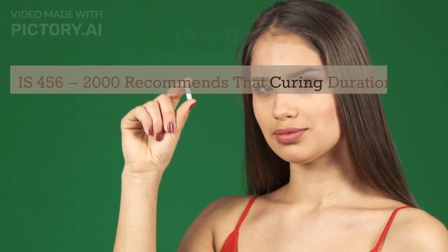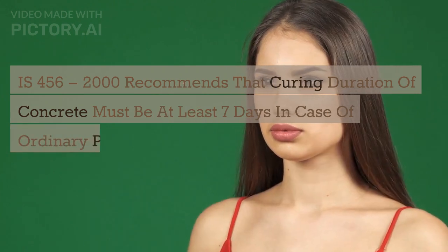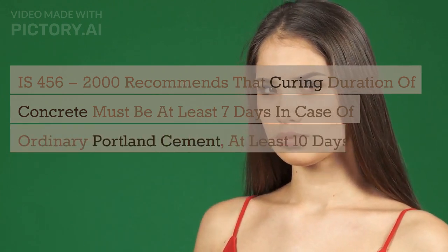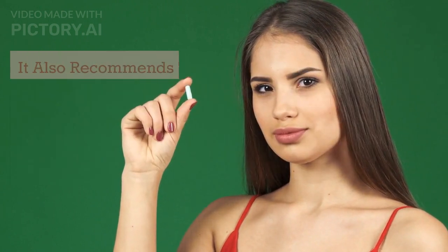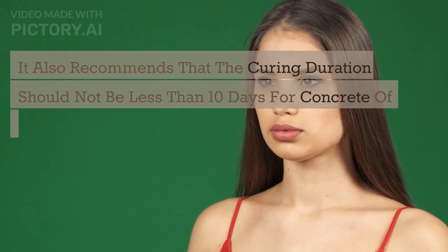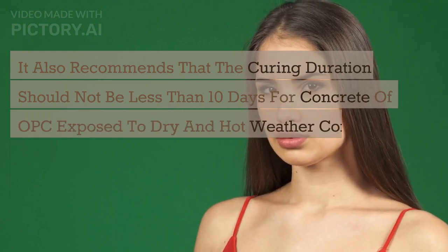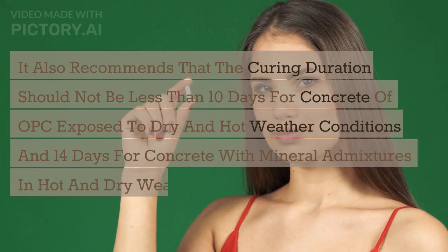IS 456-2000 recommends that the curing duration of concrete must be at least 7 days in case of ordinary Portland cement, at least 10 days for concrete with mineral admixtures. It also recommends that the curing duration should not be less than 10 days for concrete of OPC exposed to dry and hot weather conditions and 14 days for concrete with mineral admixtures in hot and dry weather.